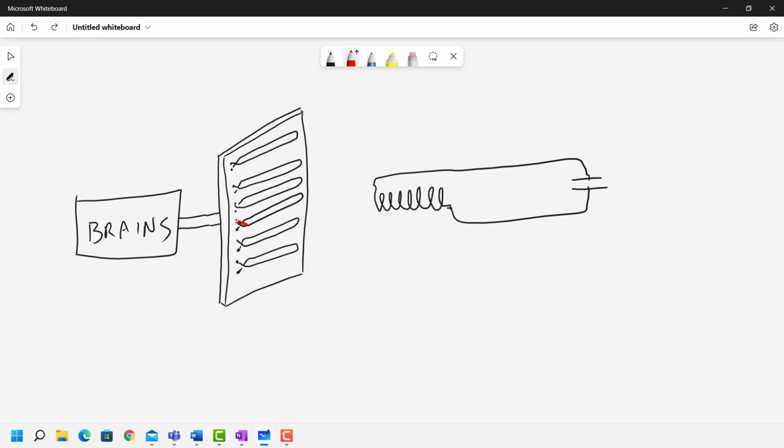What if the pen is toward the middle? Then of course one of these will register super strongly that signal, and one of these will be a little less on either side. So there are not so many coils on this board. There's not thousands, there's just a small number. There are more than this. But by looking how each one reads the pen, the tablet can triangulate, so to speak, the position of the pen, at least in this case, vertically.